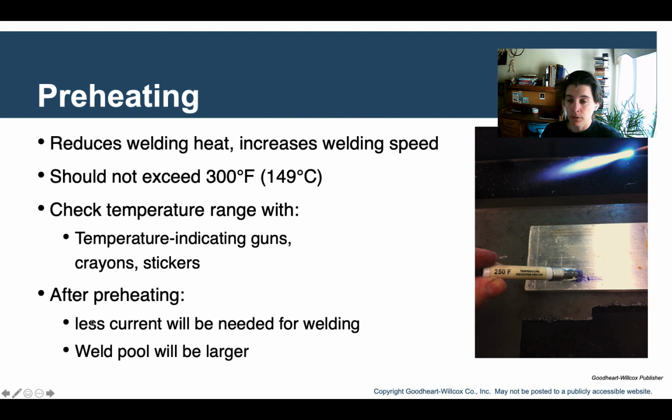After preheating, if you do a preheat, you use less current for the welding, which is good, and then the weld pool, you have to know, will be larger. So if there's something where you need to make sure there's a smaller weld pool, then you wouldn't do a preheat.